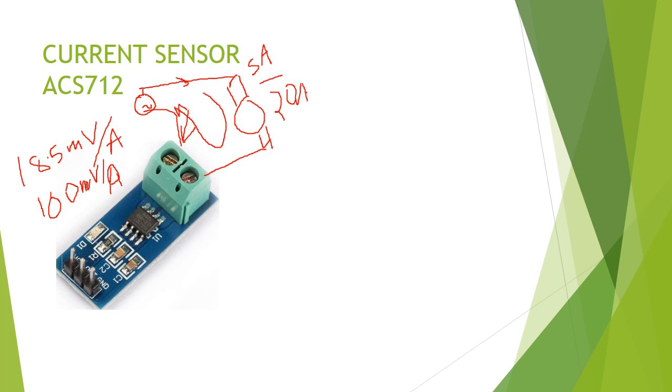So now, what is the working principle of it? Here again, this is the ground, this is the VCC and this is the data pin. Okay, so this is the common configuration. Now the input voltage VCC will be 5 volt. And one more thing we need to know is that if this VCC is at 5 volt, this data pin will never be at 5 volt.